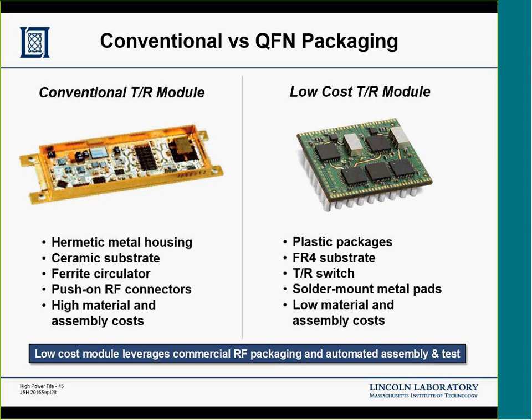And on the right is an example module that has been developed over the past 5 years or so at S-band, that you can see has many advantages because it again uses plastic packaging, a very inexpensive substrate, and this is mounted onto a PC board using solder mounting, and that's done in an automatic pick and place. So these are the kinds of things that we see as being significant cost benefits of building phased arrays.